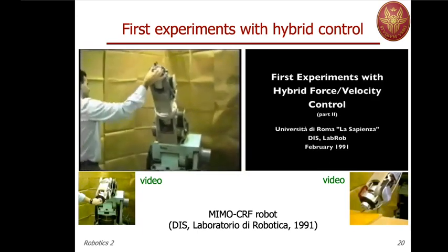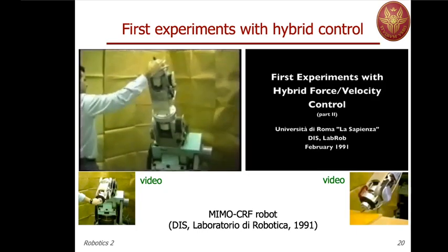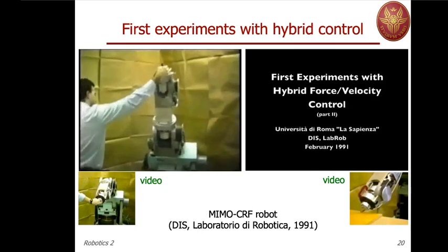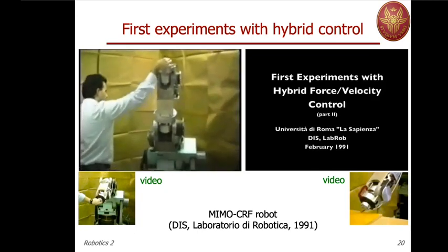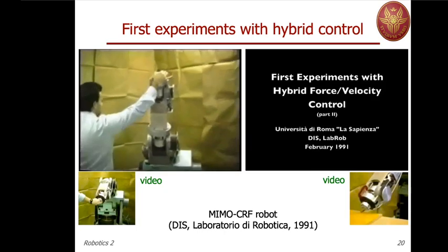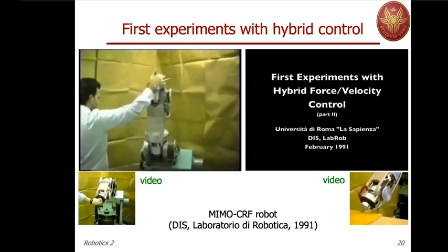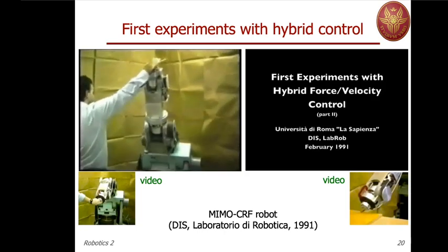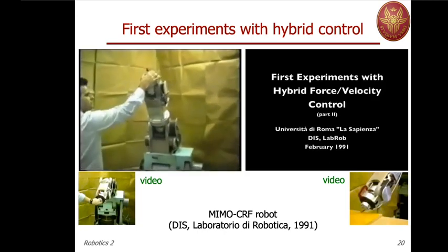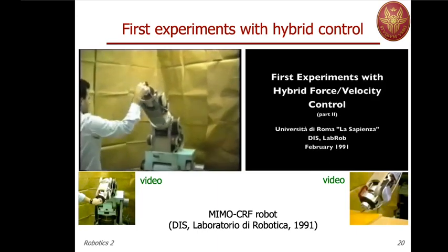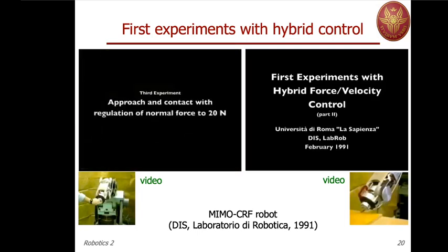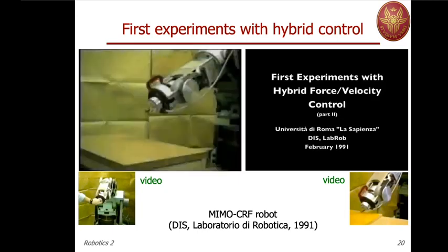And you see that if you're bringing the robot close to a singularity with the second and third link being stretched, there could be very large velocities being generated, but these are in fact damped. So by pulling and pushing the end effector and sensing forces, you still see that there is some acceleration close to the stretch configuration, but nothing too dangerous. So this was preliminary to what we've done, and in the third experiment, the last in this video segment, we